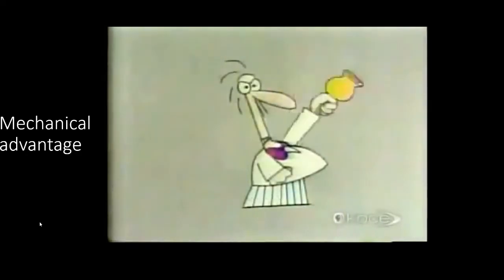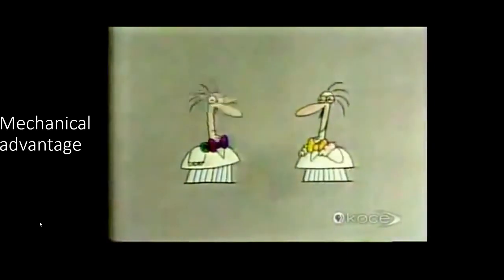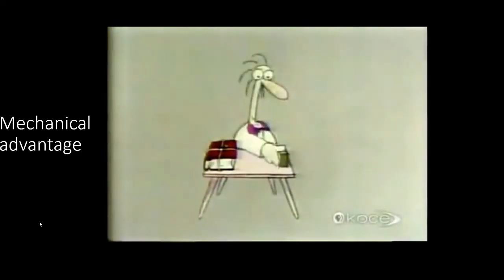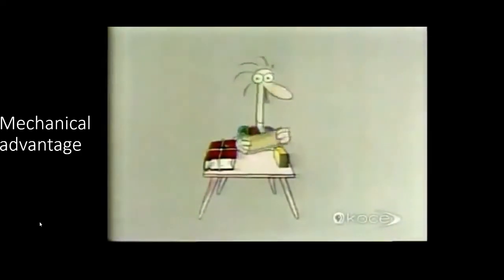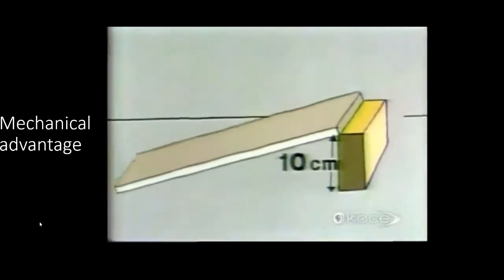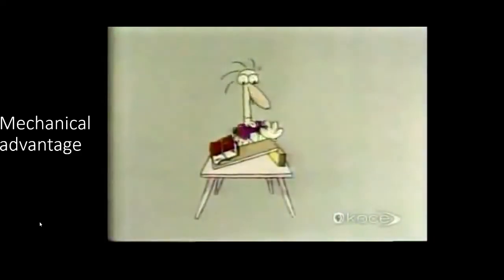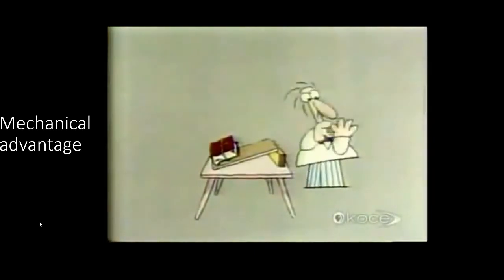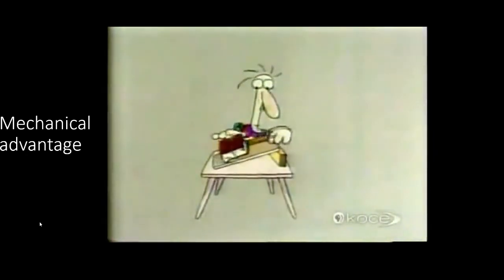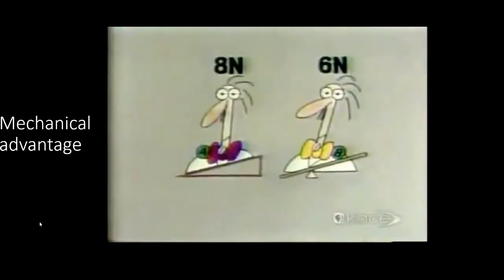You'd like us to repeat the experiment, Professor A? You think you can equal Professor B's feat of lifting the book with a force of only 6 newtons? Very well. Professor A is now setting an inclined plane against a block of wood 10 centimeters high. And the inclined plane is 40 centimeters long. Fine. That's 4 times the distance, so it should divide the force he needs by 4, which means that his Newton spring scale should read 6. What's this? 8 newtons? Well, there it is.